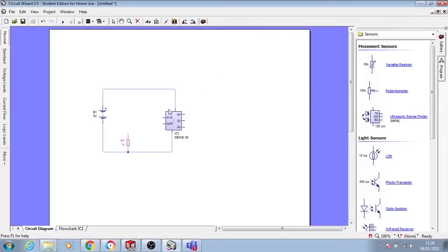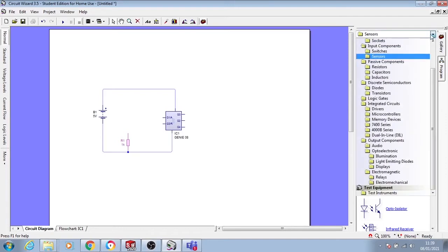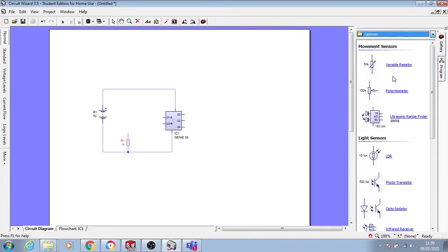And so if you're drawing this potential divider, it depends which way round you have this light sensor. So I'll do that as an example just so that we'll keep that relevant. So we'll go to those sensors and we'll just put an LDR there. Okay, and this is a variable resistor, but you might also have an actual variable resistor here just so you can calibrate.